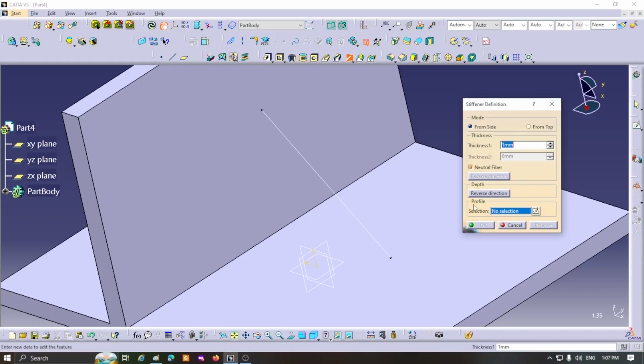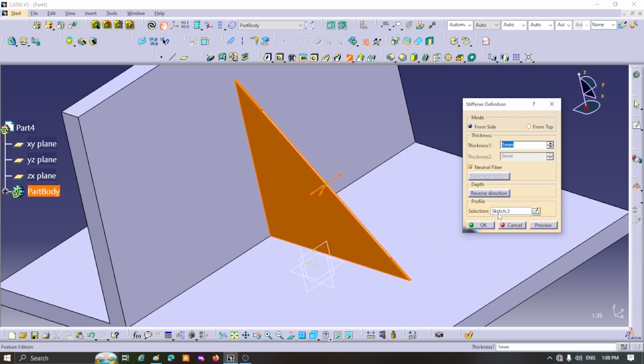In the fourth part, which is labeled Profile, we define our profile. Our profile here is the same line we drew. Now in front of the selection, there is a box that has turned blue. The familiar phrase No Selection is seen inside it. I click on the line. The name of the line sketch is seen in it. You see that a bulge has been created on both sides of the line.